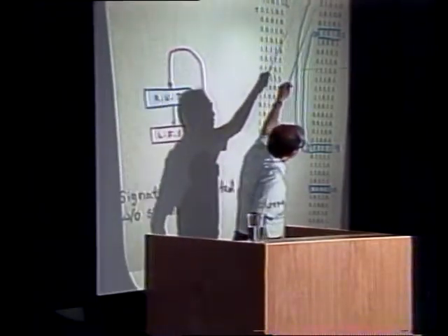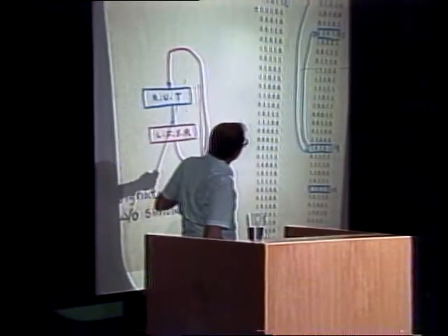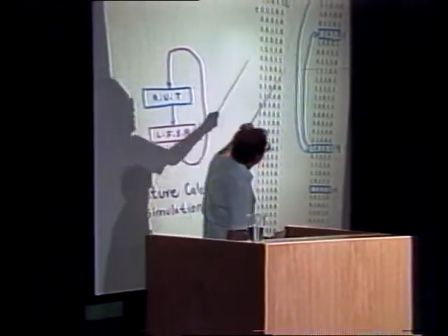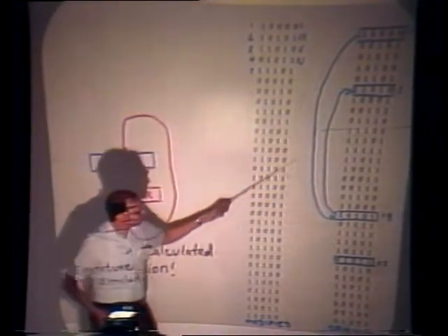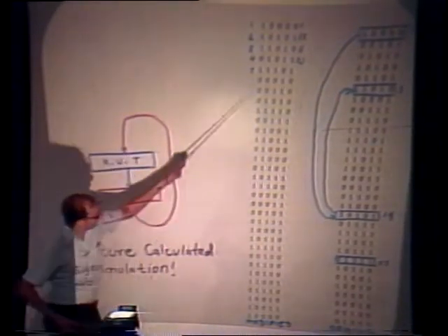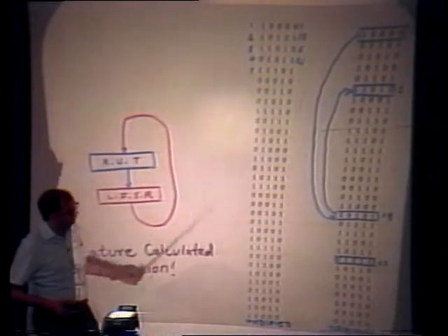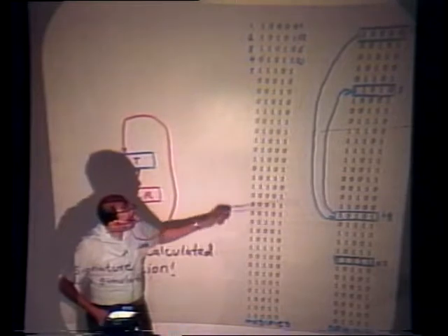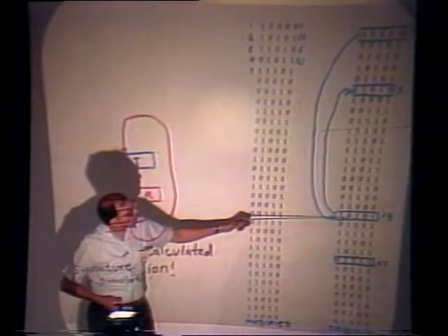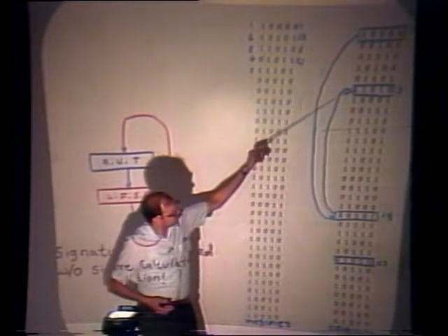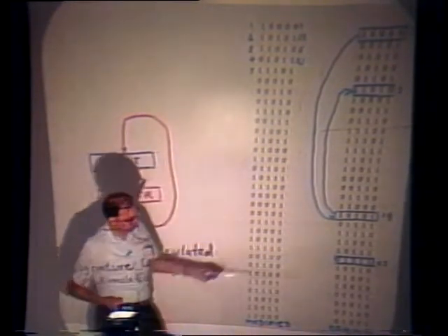Let's say we start out with that vector. We put it in this register under test, and we read it back. By doing so, instead of getting that pattern, we will jump to this pattern here. This is, by the way, what the pattern looks like in this particular mode. All right, so we jump to this vector, and then when we compress this vector again, we jump here to the pattern number 5, and then next time we go to the pattern number 23.